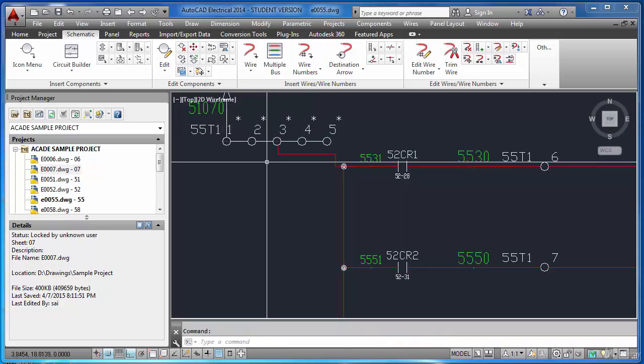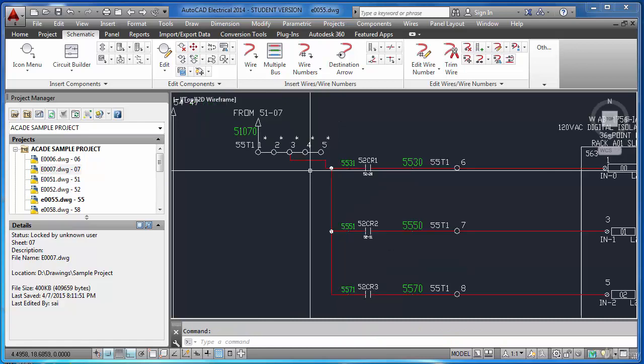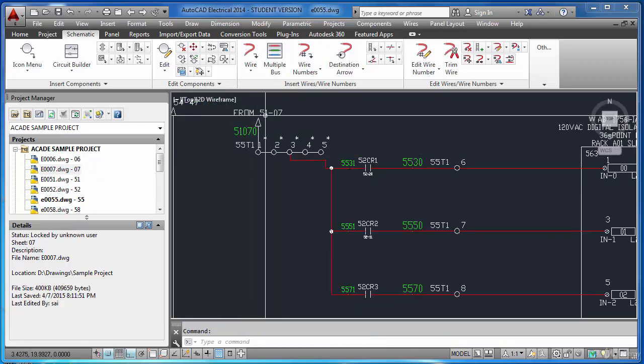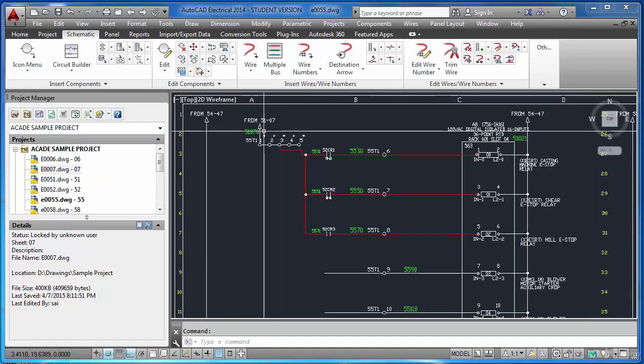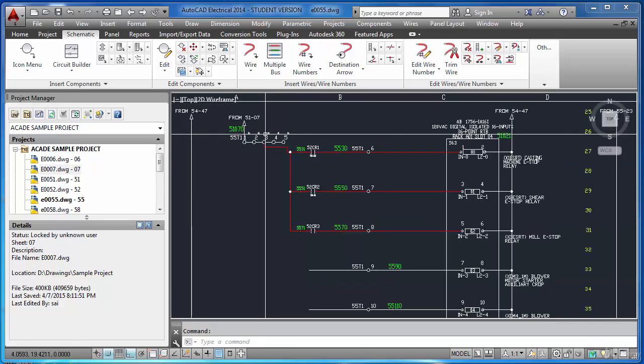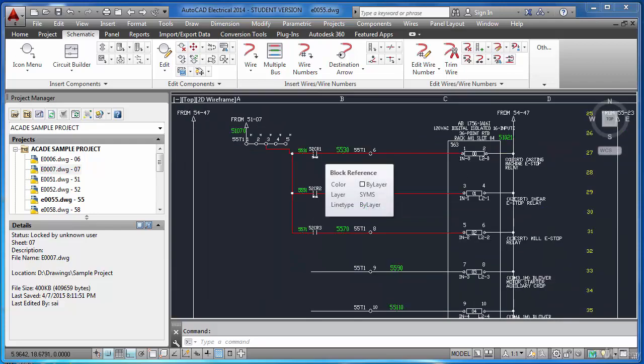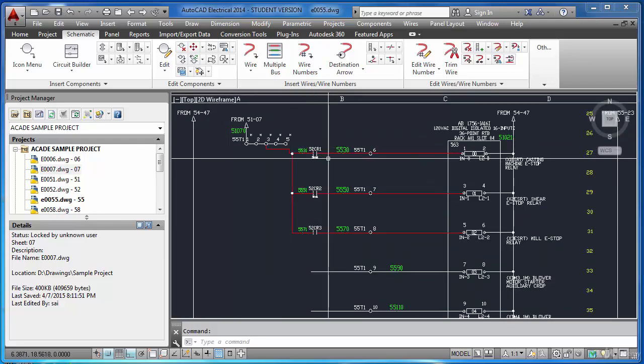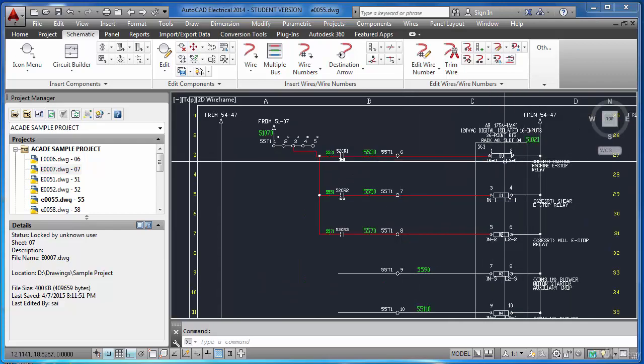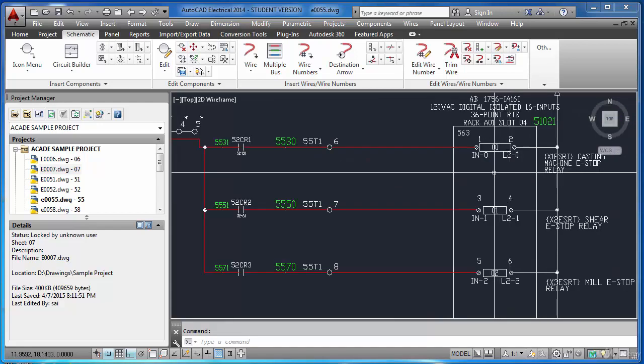I have connected to this particular point. This is some 110 volt AC coming from some other source. So basically what I did is I have used one NO contact of all the three relays here. Once that relay gets picked up, the PLC card will get a feedback.